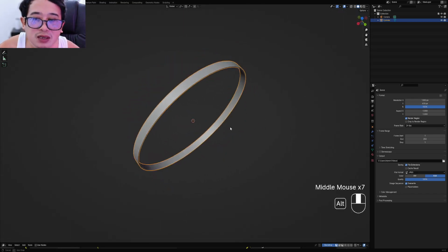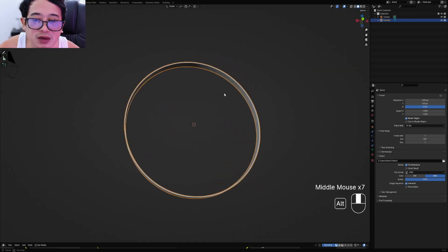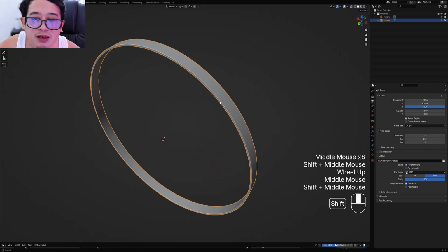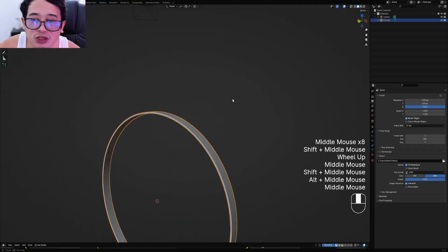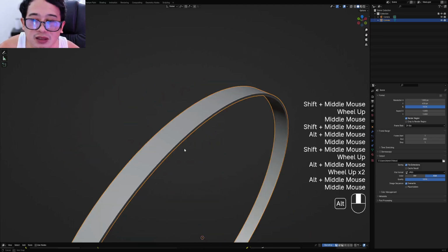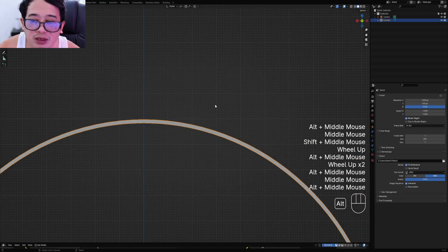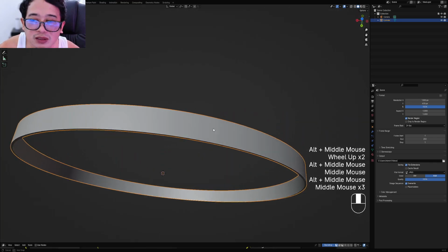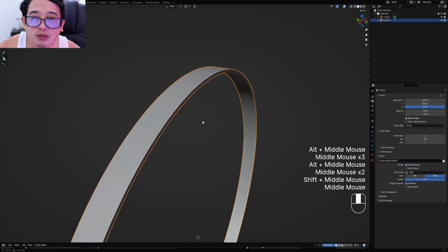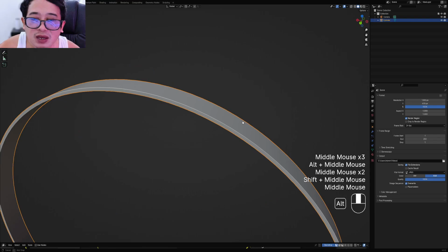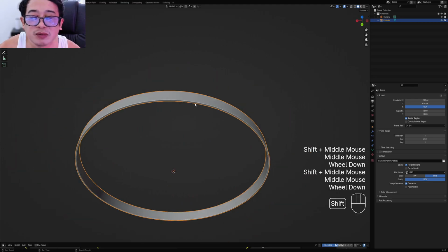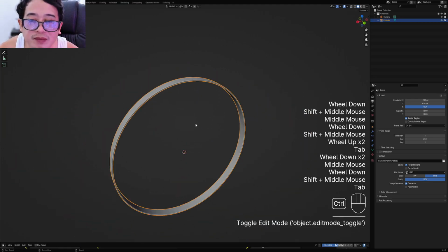Okay, so that's how I navigate the viewports. Right now I'm pressing Alt while I am rotating the viewport. I think the most important thing is the rotation pivot point, so Alt middle mouse button click. That's good. Then snap to increments of angles while you press Alt. You can press Alt along with the middle mouse button, or you can press Alt when you are nearing an axis, or 30 degrees from that. There you go. Okay, so let's go back to the model.